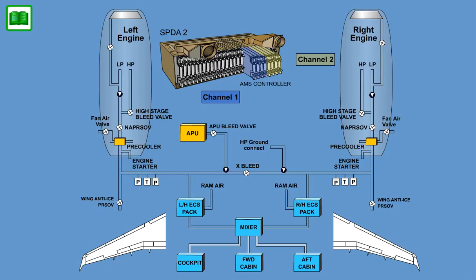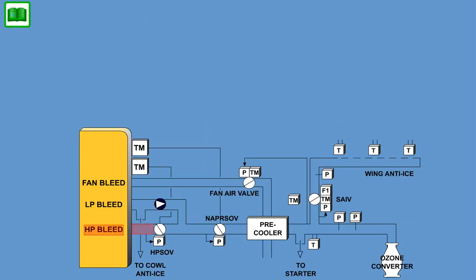The electronically controlled bleed air system provides control, electronic sensing, internal logic, and built-in test, achieving improved reliability and dispatchability. The control components provide bleed flow selection between the high-pressure and low-pressure engine bleed ports, and regulate the bleed pressure prior to delivery to the pneumatic system bleed air manifold.